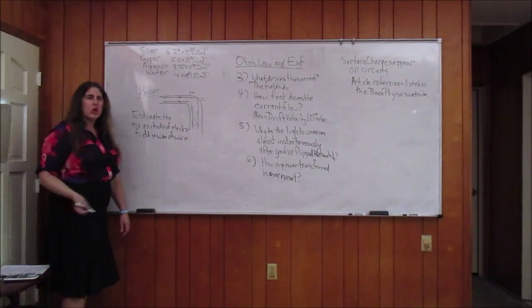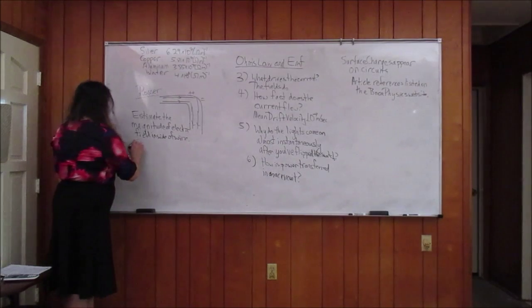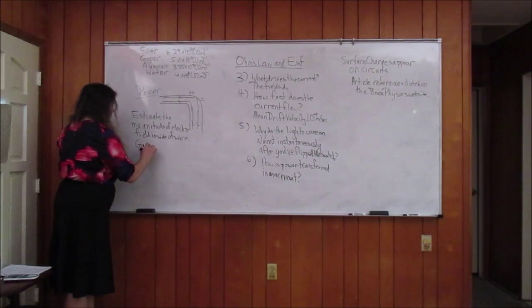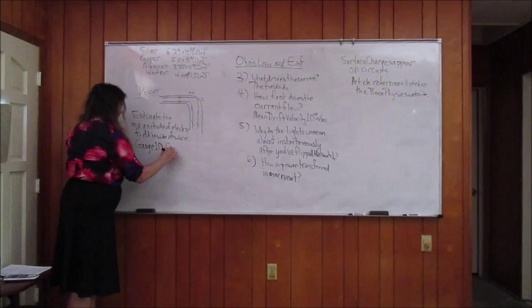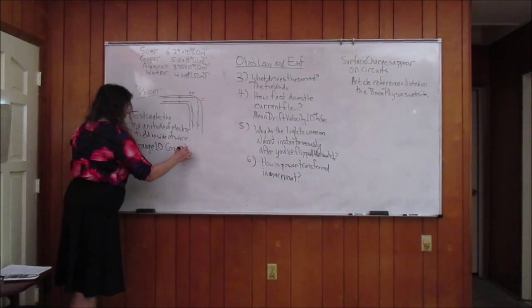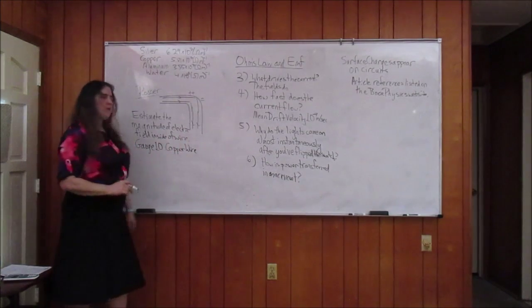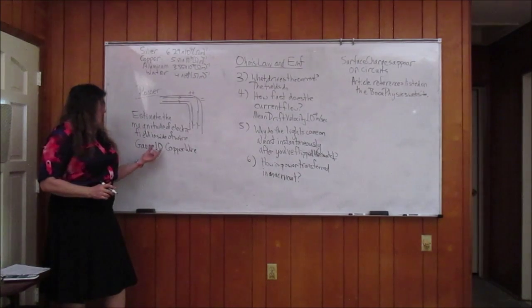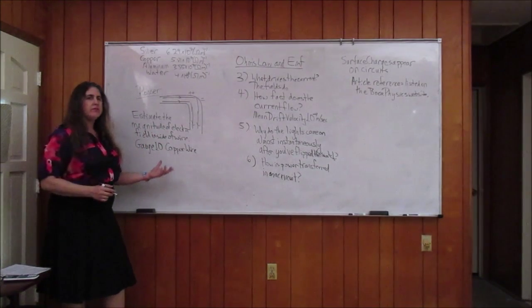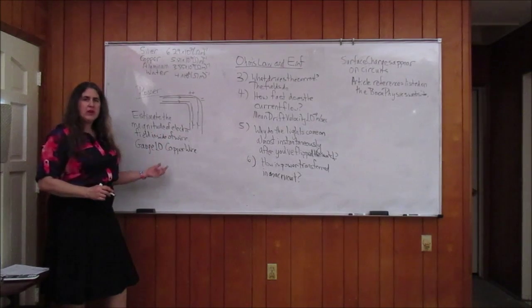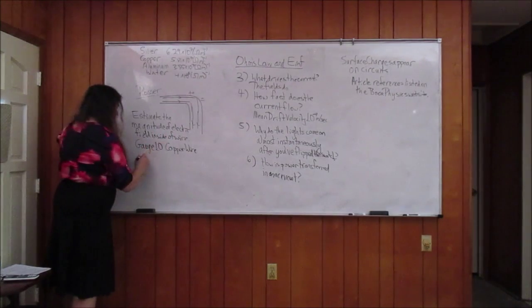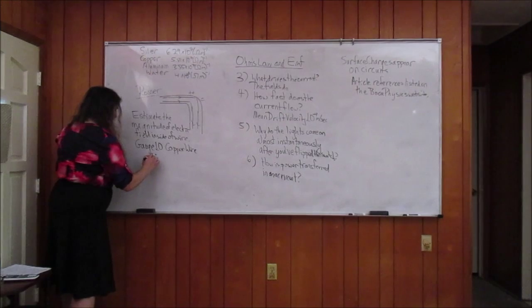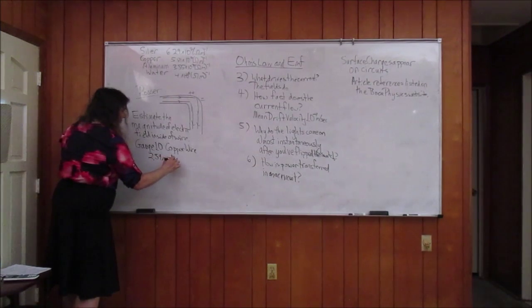To make this problem more concrete, we'll specify that we are talking about gauge 10 copper wire. And the reason why is because that's the kind of wire that's used in households. You recall about gauges, the lower the gauge, the thicker the wire. So gauge 10 wire has diameter 2.59 millimeters.